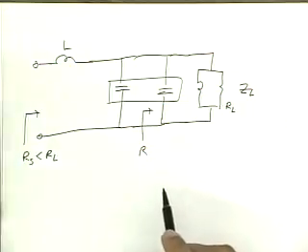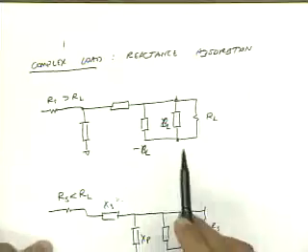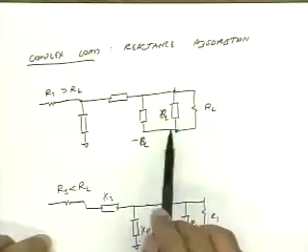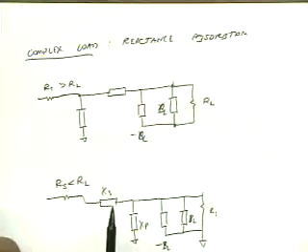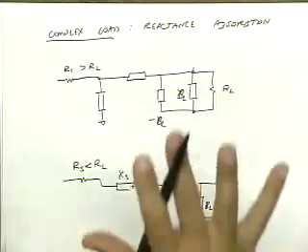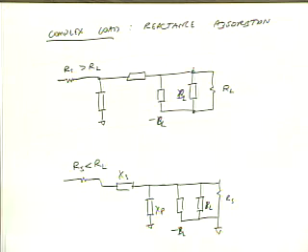That's why we call it reactance absorption, because a lot of times we can absorb the complex part of our load and source into the matching network itself. So even though the matching networks that we've discussed up to now had design equations for real loads and real sources, you can see that it very simply generalizes to complex source and complex load. Okay, any questions about that?